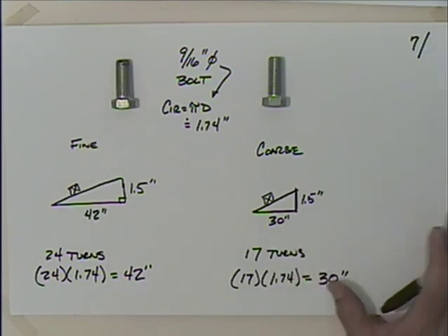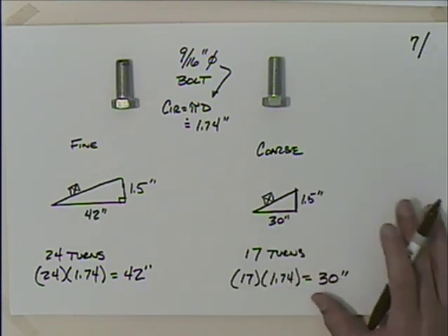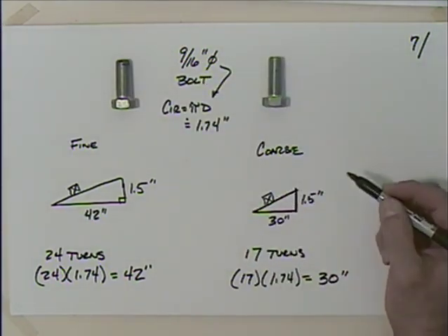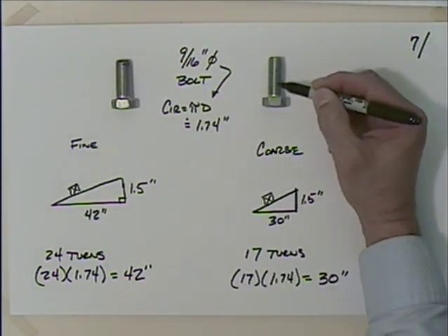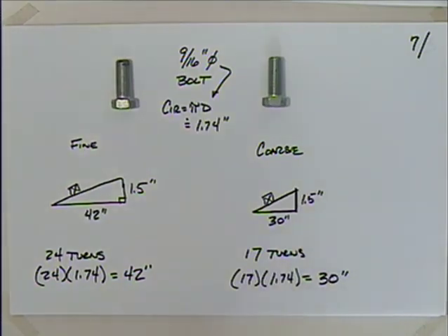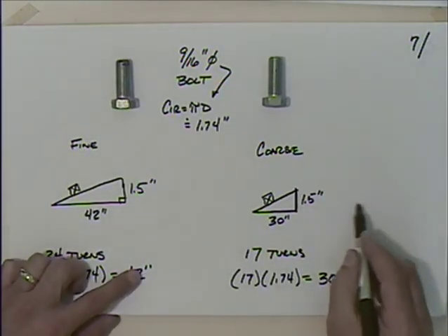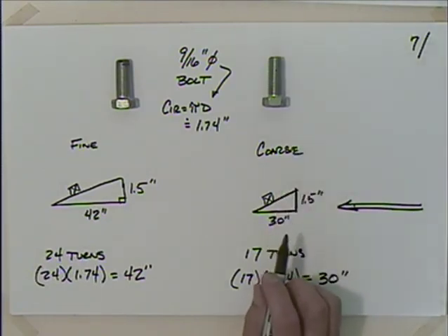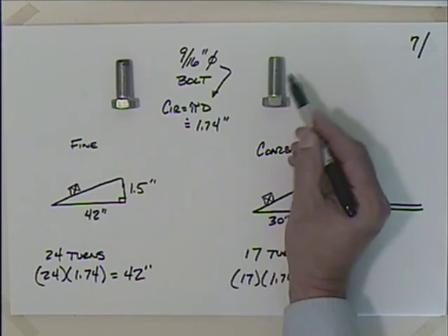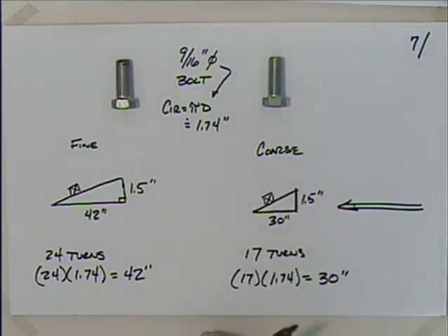Now, there's certainly practical things in terms of cutting the threads and materials, and if you're using a jack, you don't want the fine threads to get messed up. And the profile, if you're going to use this over and over again, maybe you'd want an Acme profile rather than the 60-degree profile that you have there, all kinds of things. But what I wanted to point out is you could really think of these things as a wedge or an inclined plane or a ramp. Okay, it's essentially just wrapped around the axis of that bolt.